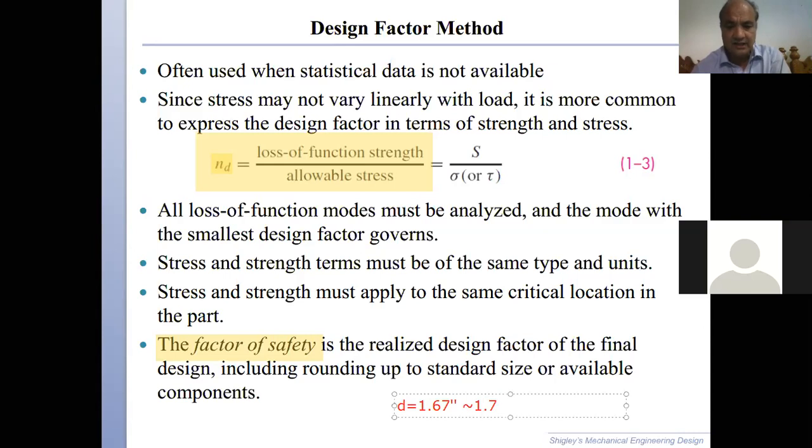And if you recall, we also said that maybe this 1.7 inches diameter is not available in standard sizes. So what would we do? We would go further, and let's say that the next available, as we said, in table A17 there are preferred sizes. Maybe let's just assume that 1.7 is not available. The only available diameter is 1.8 after this. So we will use 1.8.